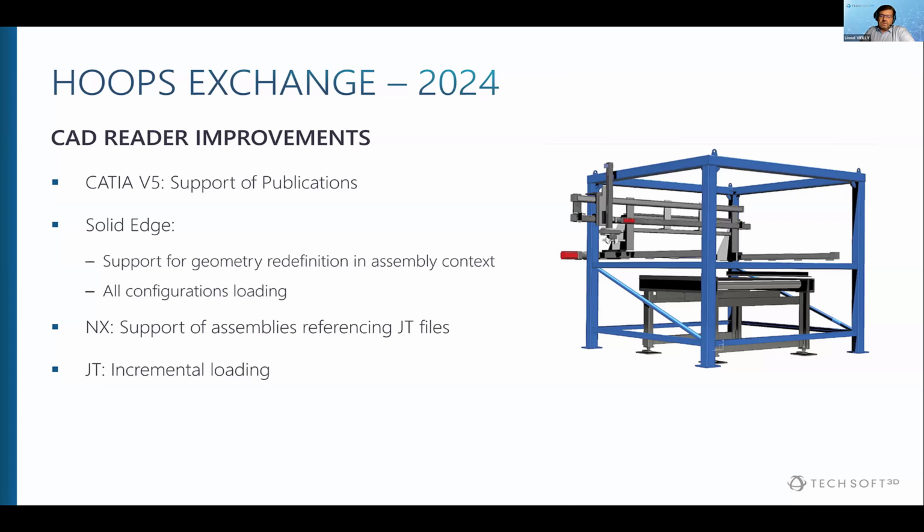And the last point here is about advanced workflow and also performance. By introducing the ability to incrementally load large GT files, so we are speaking here about monolithic assemblies, where everything is stored in one single file, having the ability to incrementally load this makes it possible to focus on a subset of the assembly and therefore to save time and limit the memory footprint.